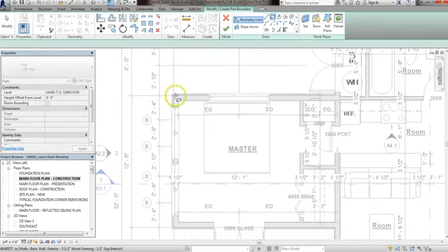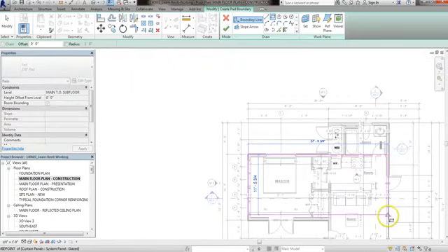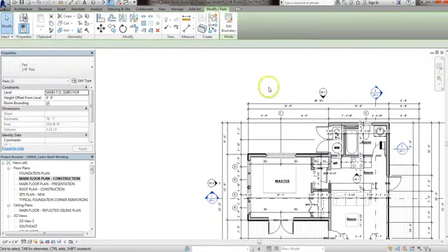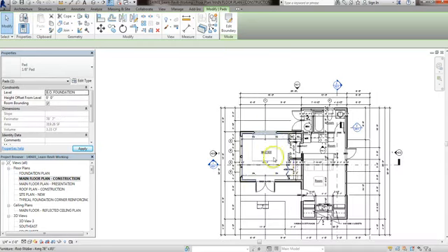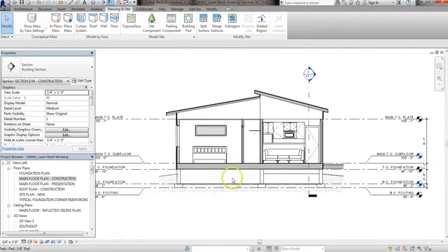And you know what? I'm just going to do this as an example. So go around, click around, outline your whole building. But I'm going to do it quicker. There we go. And we want this at the bottom of your foundation, so it'll be right on top of the footing. So now if I go to view, it lowers all the dirt that was in that region to right there. So that's how you cut that out.